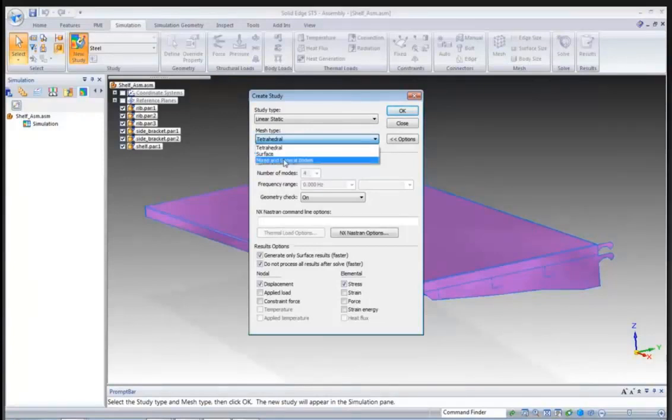And then mixed in general bodies, new with ST5, we do support a non-manifold condition. So let's say you have a turbine and you have the base of the middle of the turbine, which is a solid part, and you have the fins coming off, the blades coming off, and those are surfaces. You can join those now with unified body, even though that's really a surface coming into a solid part, which is a non-manifold body. We can do that now with ST5 simulation.